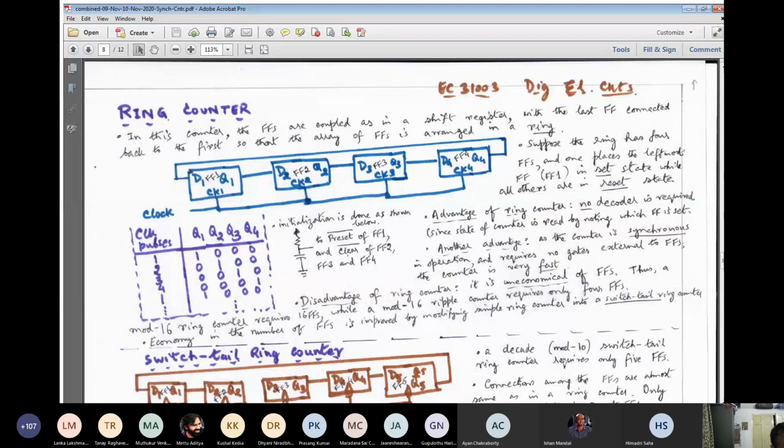We put a small RC circuit. This is the simple connection. The resistance's other end is kept at +5 volt, and the junction between R and C is connected to the different asynchronous points. The capacitance's other end is grounded. So when you switch on the circuit, in all probability, the capacitance will remain discharged, and then it will charge up via the RC time constant, 0.7 times RC.